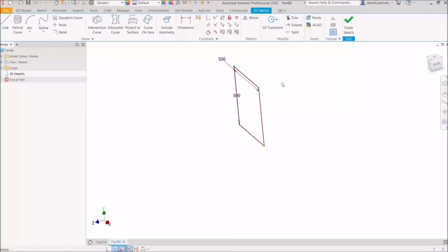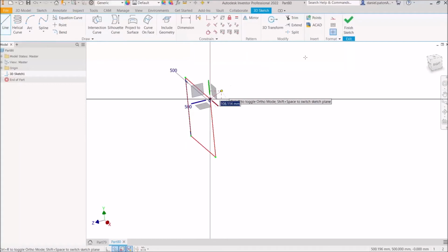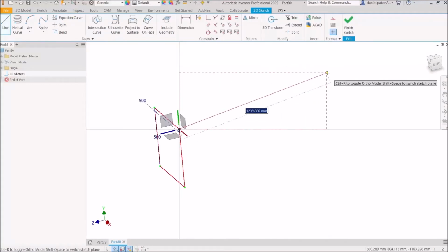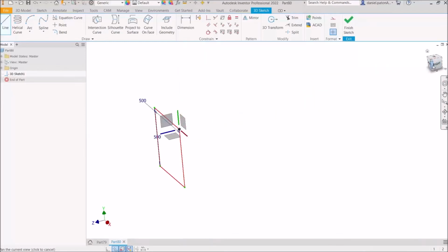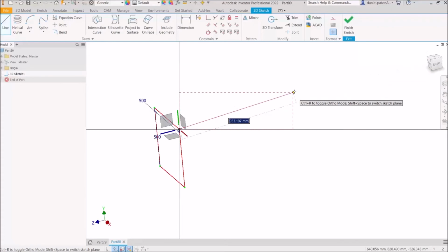And if we go and manipulate those, they change. Now, some of the other constraints that we have, I'll show you. If we go and create a line, it looks like we're drawing this line straight, because it's very difficult to tell. Again, I haven't selected a work plane and I haven't aligned my view cube correctly. So I'm just drawing sort of freehand here.